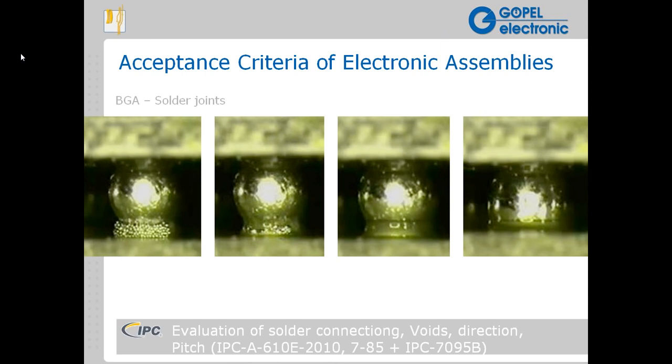Yes, I always say a healthy mix of all test methodologies available in your line is the best way to go. You need to have electrical test, you need to have AOI, and if you have hidden solder joints like BGAs, you need to have X-ray. That's the quick answer. You may run into boards that are very simple and don't have challenges, and AOI may be perfectly capable and faster, frankly. So there are possibilities where the mix would change, but as Patrick mentions, bringing all capabilities to bear gives you the greatest possible test capability.